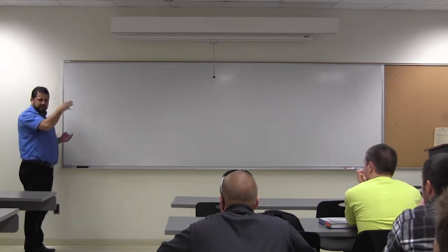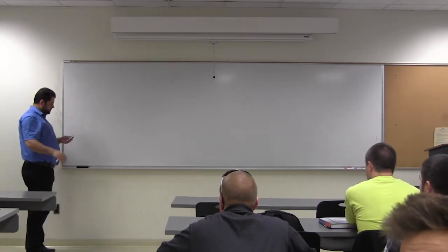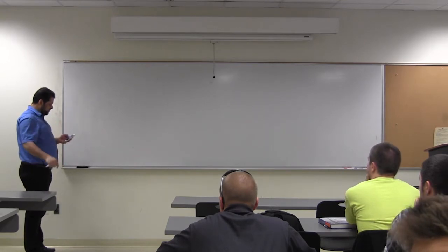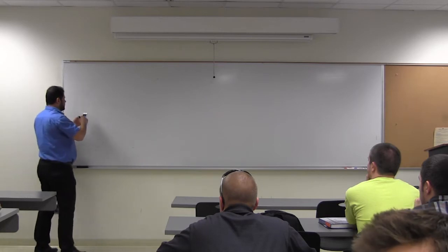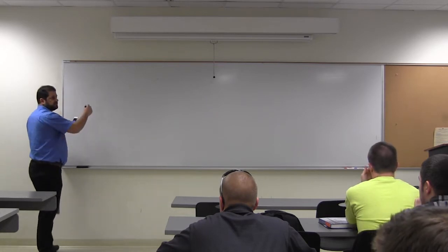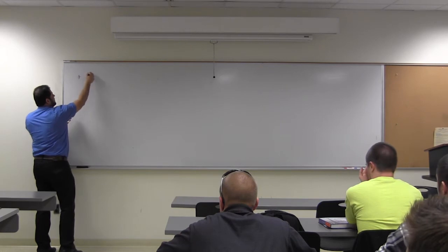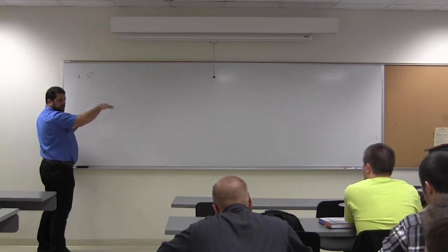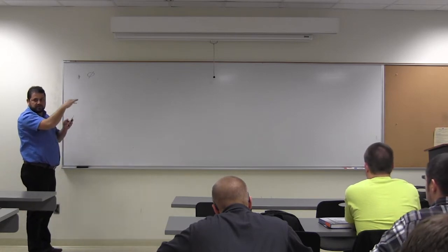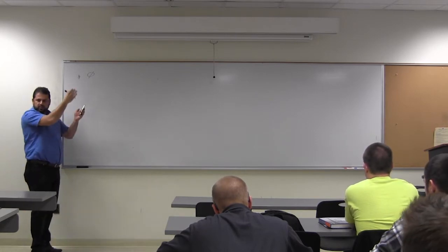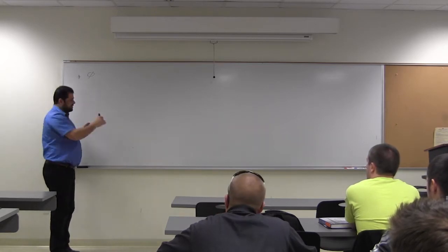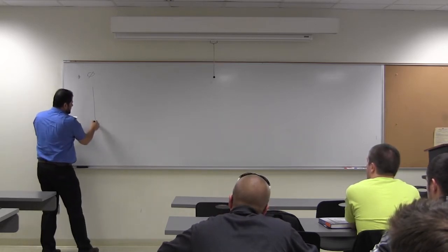There are a few things, before I go into a real design example, some notes, just to make sure you have a complete set of handouts or notes. Remember when I talked about the strength reduction factor, the Phi factor? I gave you the graph. I said there's one for tied members, or ties, or spiral. The spiral is for columns. The ties, that's for beams, depending on the stirrups for the shear design. So it starts like that, right?